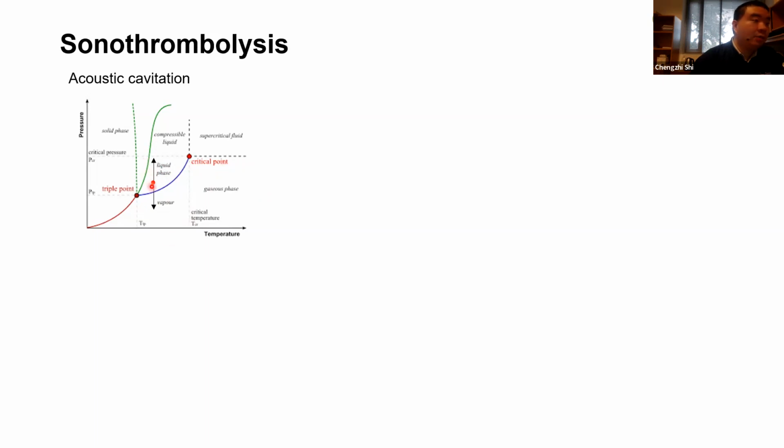But for acoustics, we are not trying to change the temperature. Instead, because an acoustic wave is a pressure wave, we can result in oscillation of the pressure. And once the intensity of the ultrasound is high enough such that the pressure can bring this phase diagram down into the vapor phase, then we will result in the formation of bubbles. And that's the working principle of cavitation.